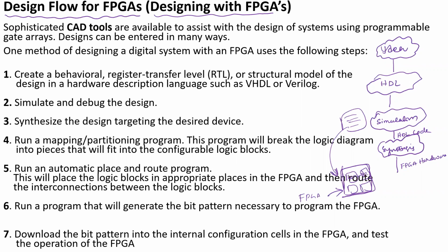Once the synthesizing is done, then what we have to do is map your design. Mapping your hardware into a real FPGA. These are automatic tools that are available. So only the humans are involved here: they have an idea of the specifications, and they write them in the form of HDL code. Only the designer will focus on this one. Remaining all these things are done by the automated tools. For the simulation an automated tool is there, for synthesis an automated tool is there, and mapping will also be done by an automated tool.